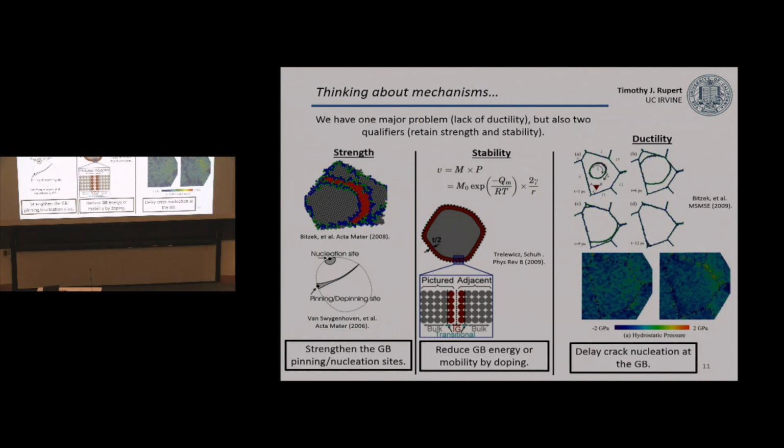And if you look at this top figure, you say, the dislocation's there, poof, it's gone. But something important happened when that dislocation got absorbed. We changed the boundary structure. If we look a little bit more closely before deformation and after, and we look at the local stresses. The big benefit of computer modeling is we can go and look at atomic scale features that we can't see in an experiment. They could see that one of those boundaries started having these bright spots.